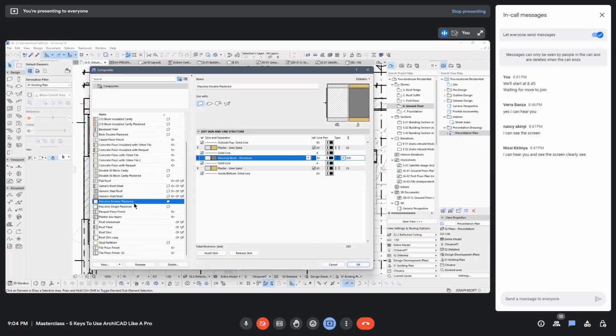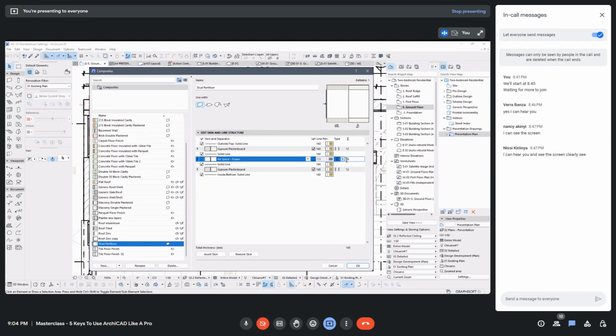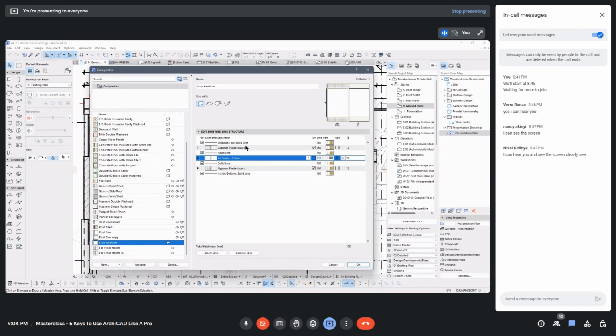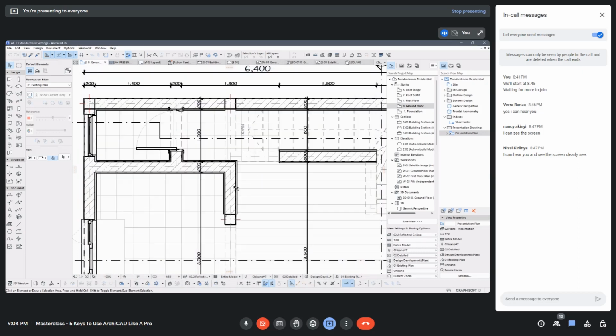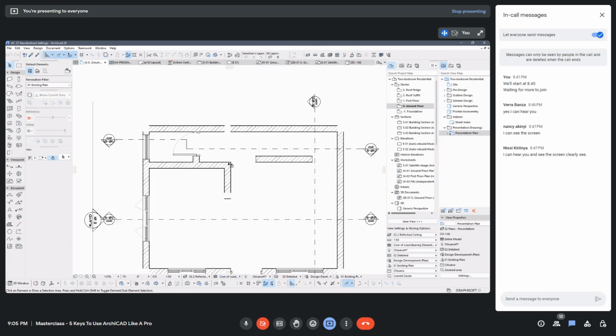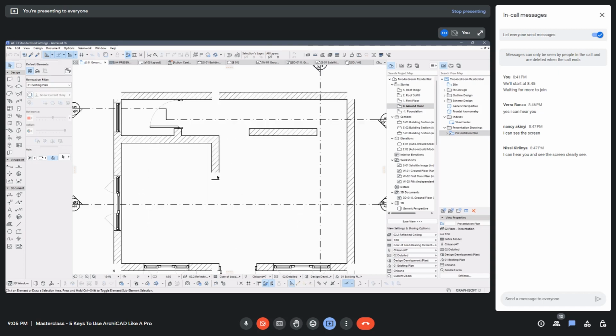If I'm working with timber and it's a stud wall, then there's airspace in between. That's where the structure would be, and the gypsum plaster board on either side will be the finish. So maybe have this airspace in between and then arrange my studs in between. But that's on composite. So that's what structure display is for. Yeah, so I need to be able to have control over this. So I can even go further and say it's the core of load-bearing elements only.